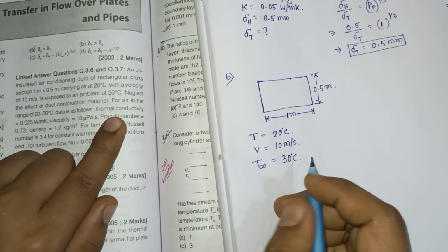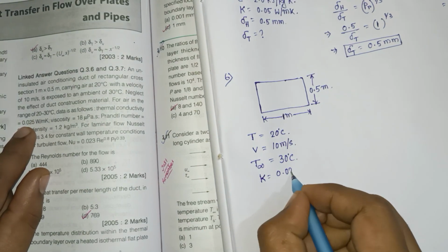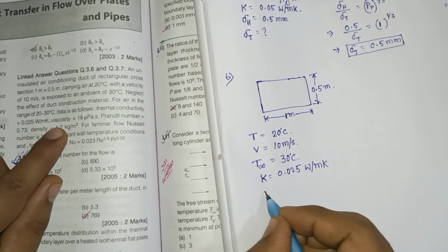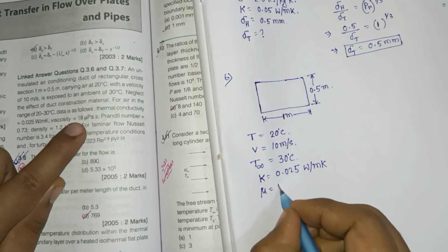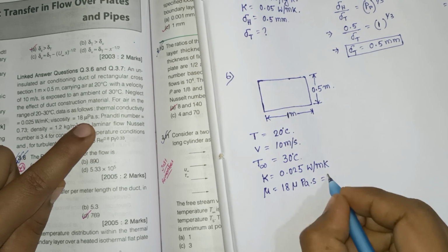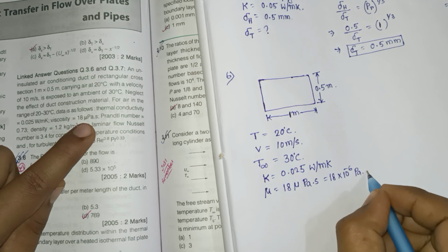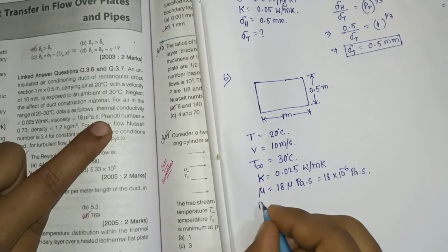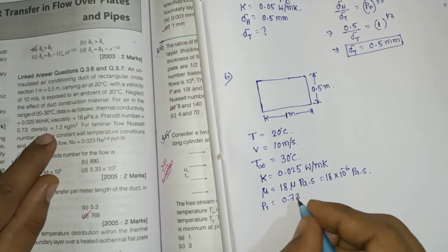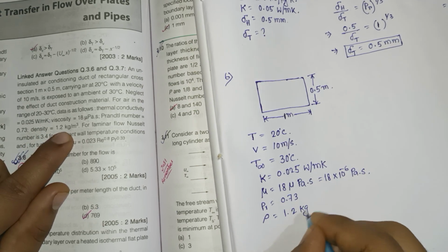For air in the range of 20 to 30 degrees Celsius, data is as follows: thermal conductivity K is equal to 0.025 watt per meter Kelvin. Viscosity mu is equal to 18 micropascal second, that is equal to 18 into 10 to the power minus 6 Pascal second. And Prandtl number is equal to 0.73,